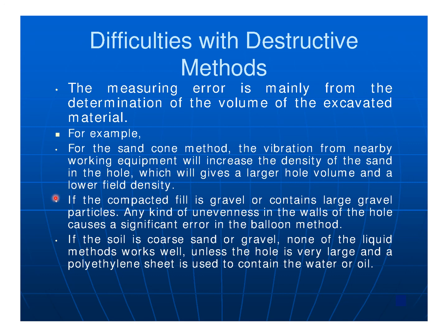If the compacted fill is gravel or contains large gravel particles, any kind of unevenness in the walls of the hole causes a significant error in the balloon method. If the soil is coarse sand or gravel, none of the liquid methods work well, unless the hole is very large and a polythene sheet is used to contain the water or oil.